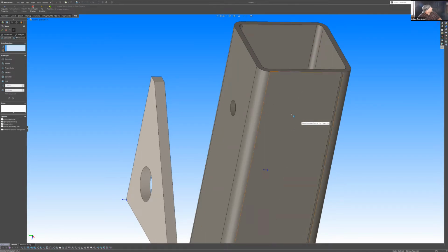Oh yeah, Shift Alt. Transparent is my favorite color. So in that option, the Alt key makes it transparent, so you can click the face behind. Shift Alt brings it back. But that's only effective in the mating scene. You have to have mating enacted before it works like that.